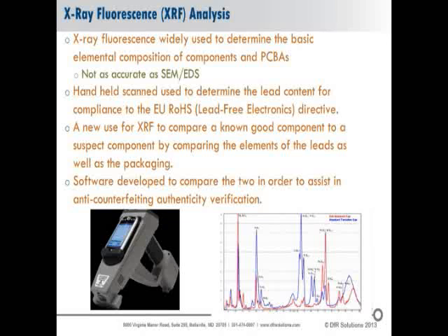Another way it's being used is they're looking at the material characterization of different components, particularly the leads, to see if they match or not. And if they don't match, that's indicating that you possibly have a counterfeit part here that is coming from a non-factory source. So this is a new and interesting tool.